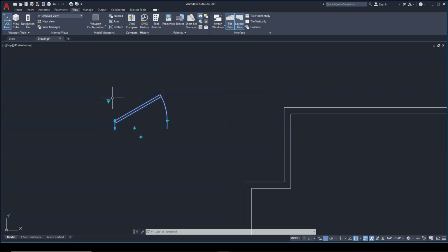For instance, when I click on this grip right here, it allows me to change the door opening. So if right now it's set to 30 degrees and I want the door to be open 45 degrees, I'll just click 45. There it is, done for me. Or 60 or 90. There it is, 90. And if I want the door closed, there's the door closed. So this is cool. I can change my door from 45 or 30 degrees to a 90-degree door.